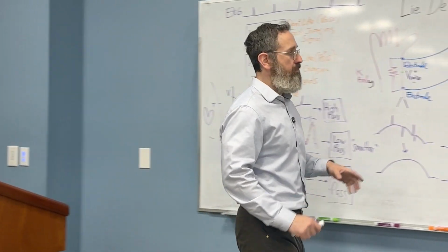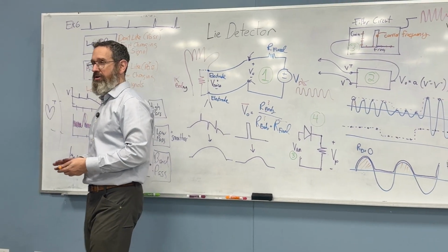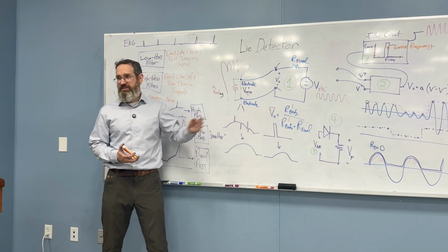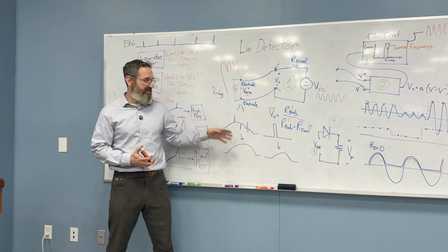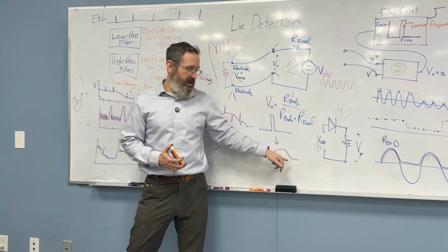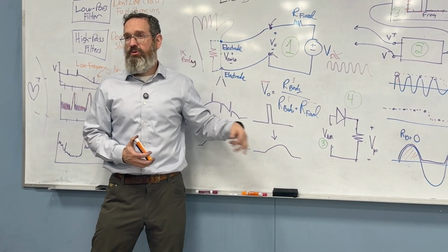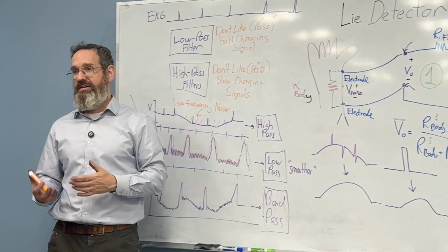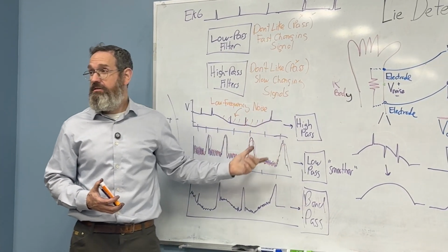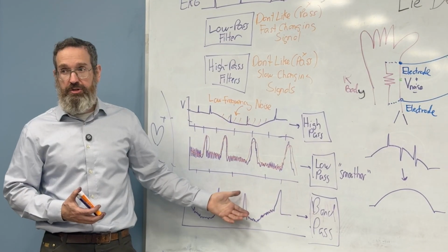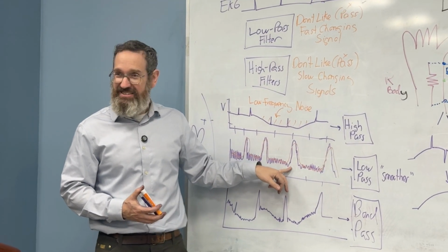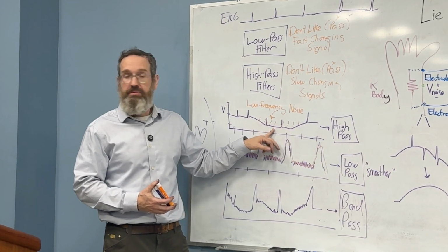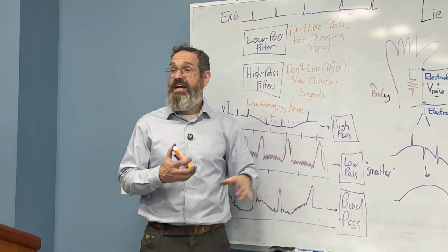I think what I'll probably do is send you, maybe your homework will be to just watch a couple of things about modulated and demodulated signals, so we'll go back over what I said. And I'm going to have to think a little more about how to make this more intuitive to you. When I or Professor Demachowski or Professor Parra are thinking about designing filters, we actually start here. We start with, is the noise fast compared to my signal? Low pass. Is the noise slow compared to my signal? High pass. That is actually where we start.